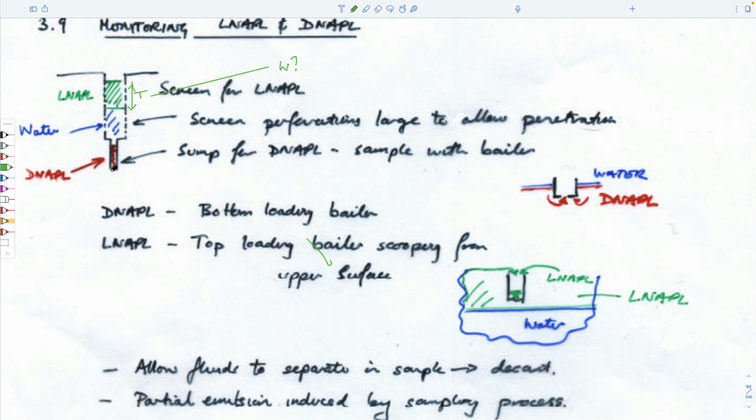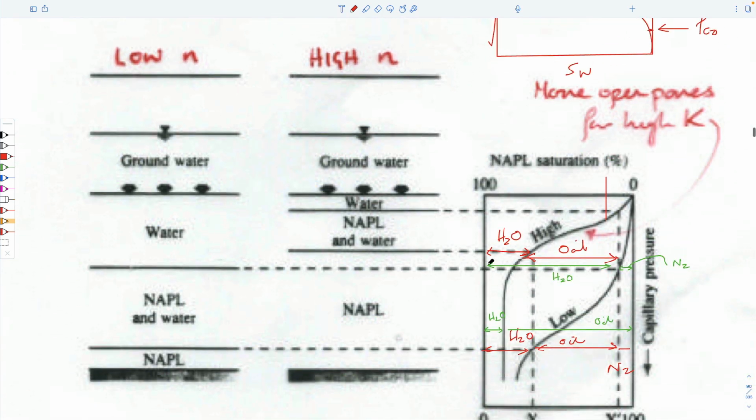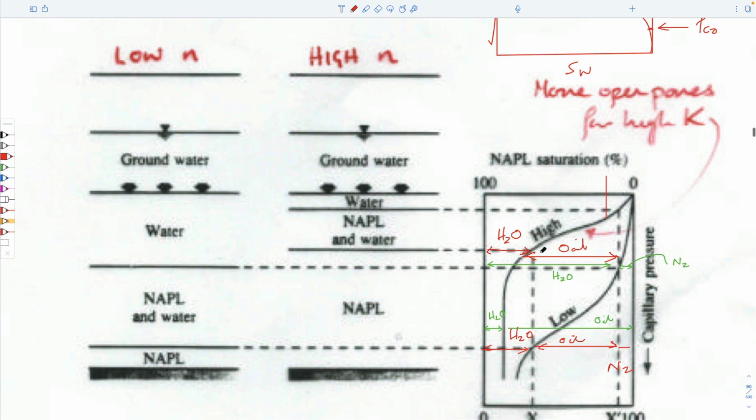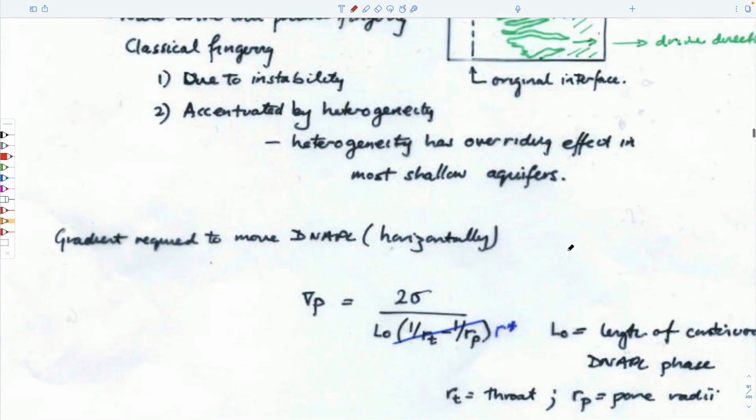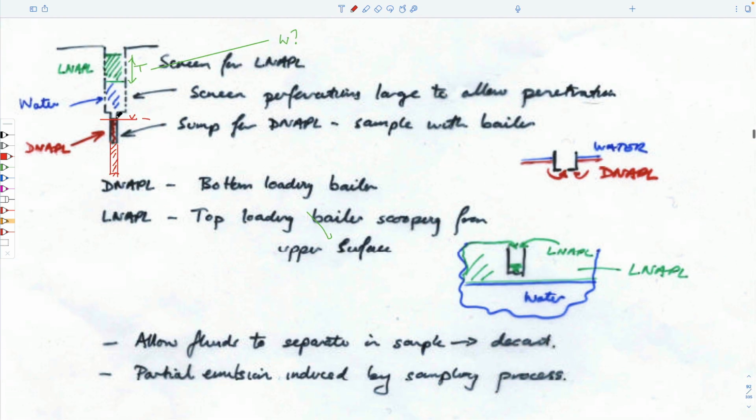If we drill the borehole through a DNAPL contaminated site, the deeper we drill the borehole, that borehole will just keep on filling with the DNAPL. If we drill the borehole deeper, so long as there's a supply, it will keep on filling up. So the only thing that's relevant to us is the upper reaches of this, which will represent a portion on the capillary pressure curve where it saturates to one of these high magnitudes. So that's what that point there represents.